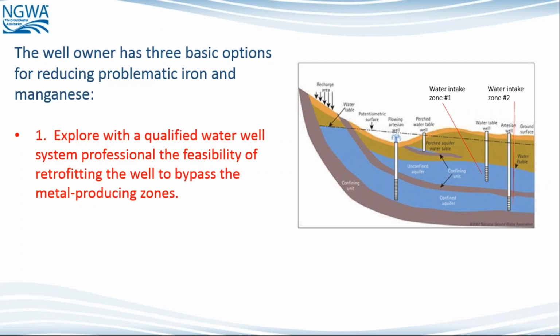This application would be very specific to an issue that we knew or were able to evaluate, that certain flow areas of the well were producing the iron and manganese concentrations. However, if we didn't know that, it may take some evaluations, through a literature search for example, to know that wells in the area at certain depths provided high iron and manganese.